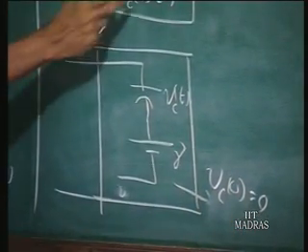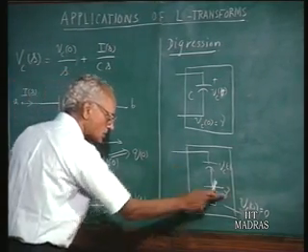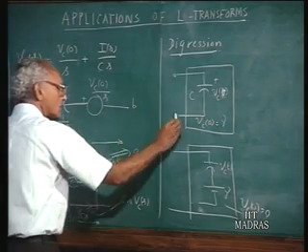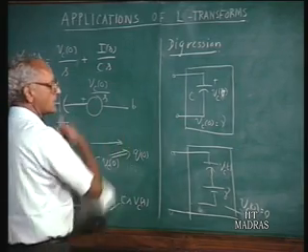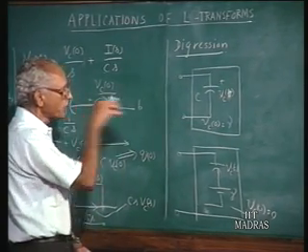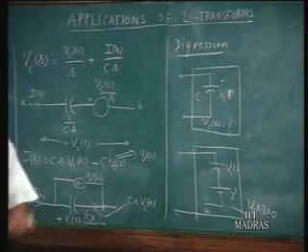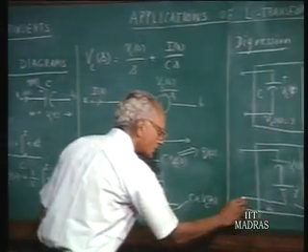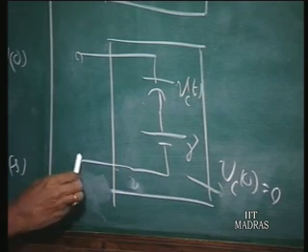So we have two situations. One, a capacitor which is charged initially to gamma volts, and another, a capacitor in series with a voltage source whose value is gamma, but the capacitor itself is initially uncharged. So if these two capacitor systems are given to you in two black boxes, they provide identical terminal relationships to whatever circuit they are connected to. In other words, from any external measurements, you will not be able to distinguish between these two. They have identical terminal relations for all possible experimental situations. These two are equivalent for every conceivable excitation.